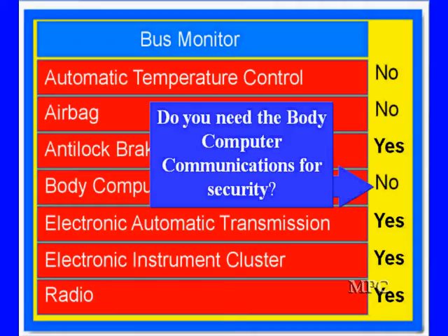Every day on IATN, I see somebody saying, I've got a car that won't start. What do you think it could be? And they get a lot of suggestions and very few answers. It says, do you have communications? No, I've got a U code. Duh. If you don't have communications, your security system, if that's the bus that's down, may not be able to talk. This is a big part of the situation. So keep this in mind.